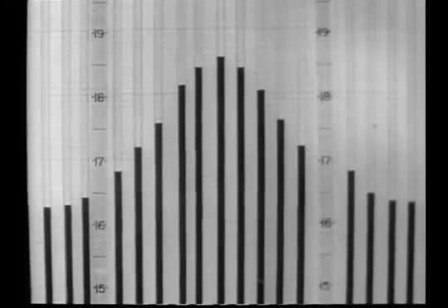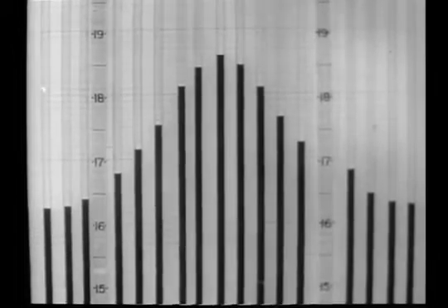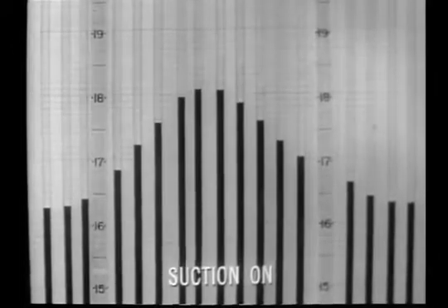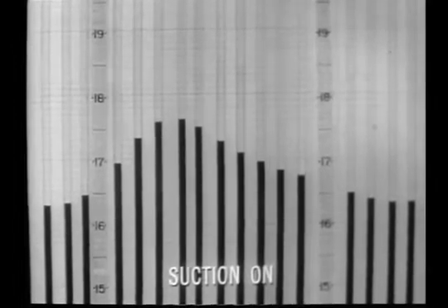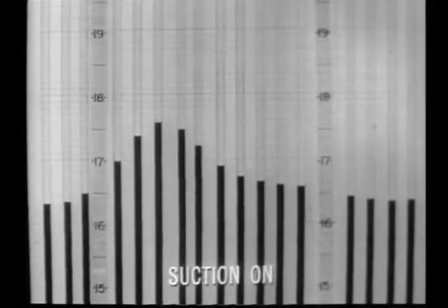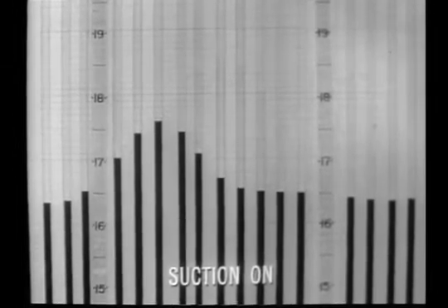Power is needed to achieve this drag reduction. The optimum condition occurs when the total drag, the aerodynamic plus suction power converted to an equivalent drag, is a minimum.